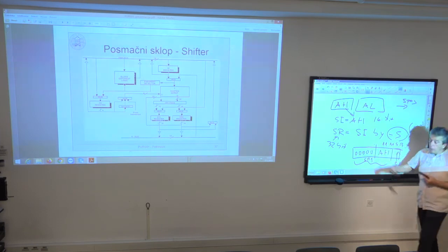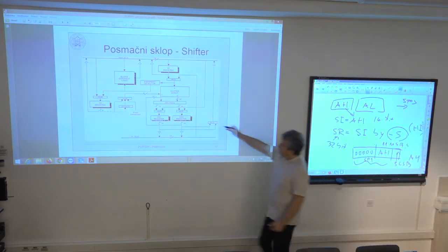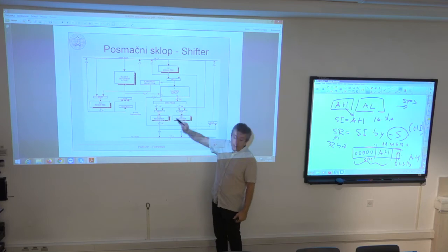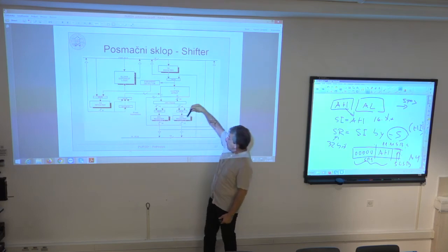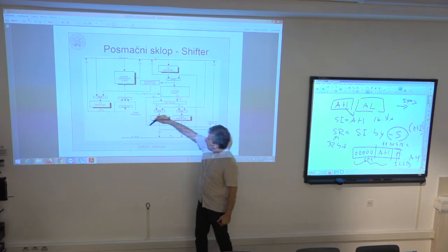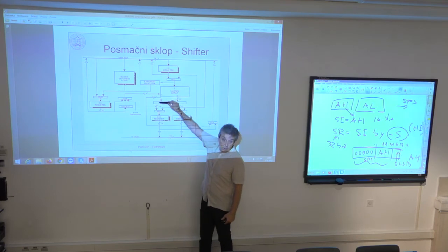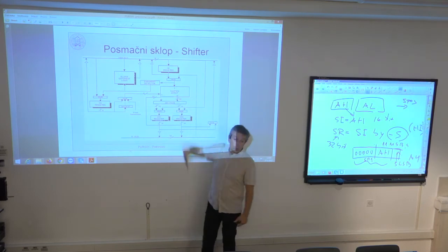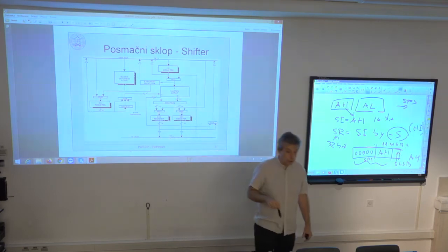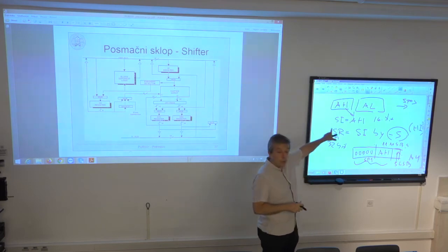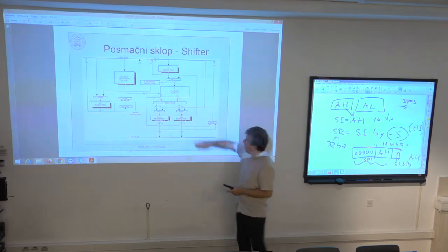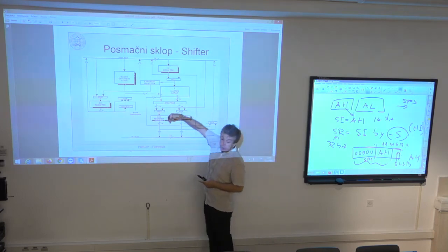So this ORing logic is shown here. It can be activated or not. So if I activate this ORing logic, then simply the 32-bit result from the previous shift is fed back to this OR logic, which is combined to the 32-bit value of the current shift. So for example, if I performed first the upper word shift, I have this result across both of these registers.